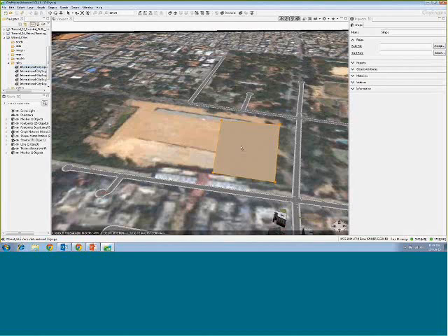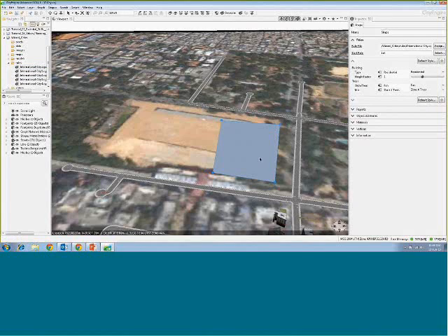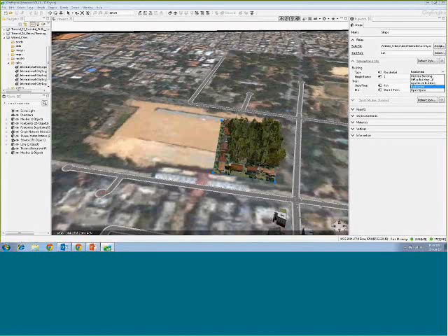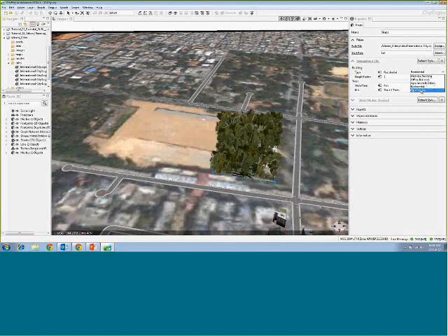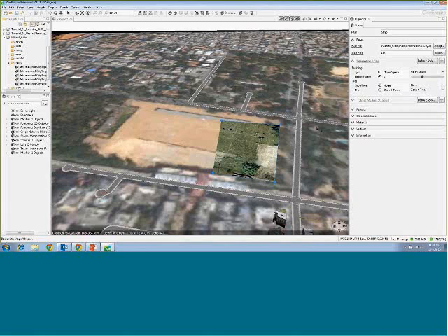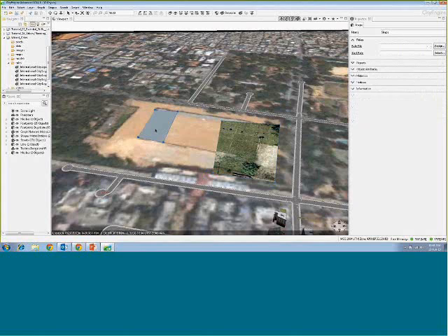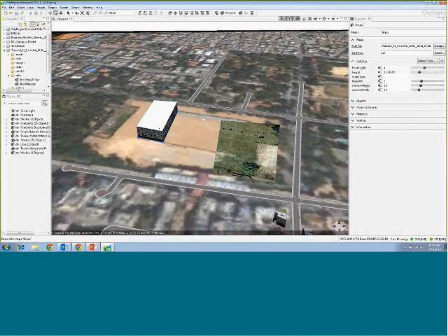Going ahead, we can create one more plot right beside that. This plot could be aligned to different types of buildings. Going ahead to the most tutorial which you may use, a building.cga rule, I apply it on this particular building. It models my building on the fly. Now here you have controls over deciding upon the floors, floor height as well as overall building height. Selecting my model, I get functionalities to control my floor height or the overall height of the building.